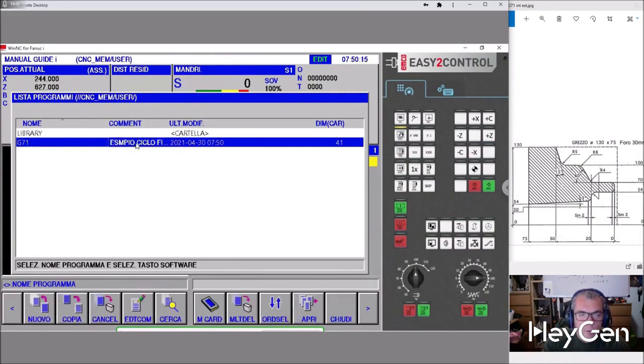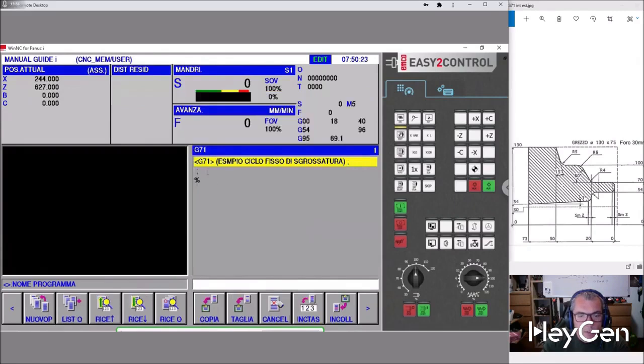Honestly, folks, for example, a fixed roughing cycle description might suffice initially. Let's check whether space is accepted correctly. Not every CNC handles spaces inside comments equally well, some requiring underscores instead. Opening it up reveals an empty little program space, ready and awaiting input.